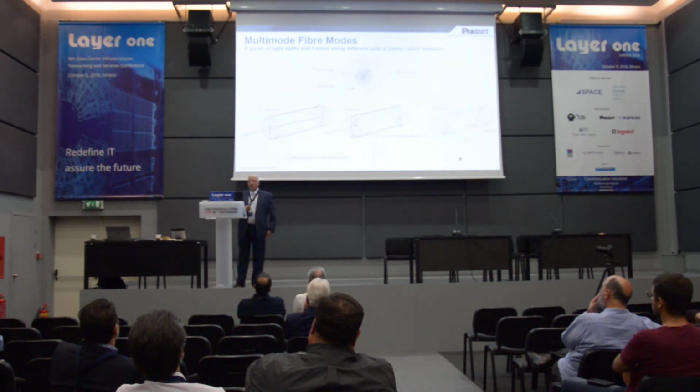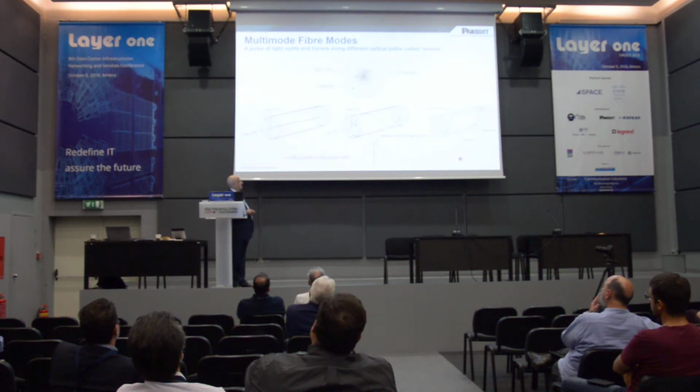And what I show here are 3 examples of modes. You have what's called low order modes, which propagate close to the fiber core. You could have ones that look sinusoidal, kind of like a guitar string. You even have modes or paths that take corkscrew paths. So what you can see is if light goes straight down the fiber, it's going to get to the end of the fiber quicker than, say, light that's going down some other more complex path.